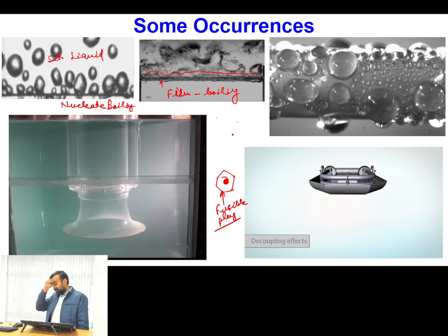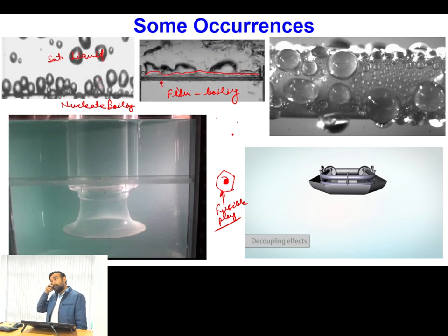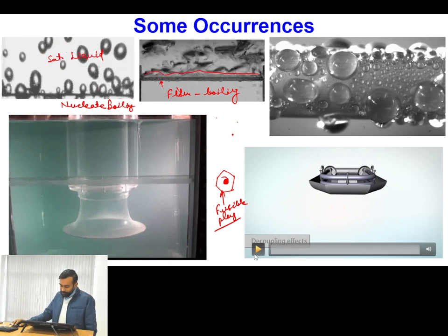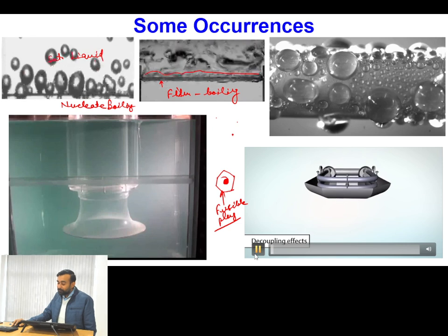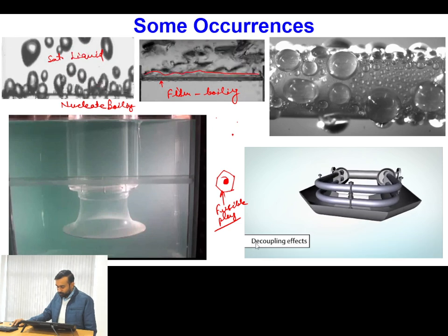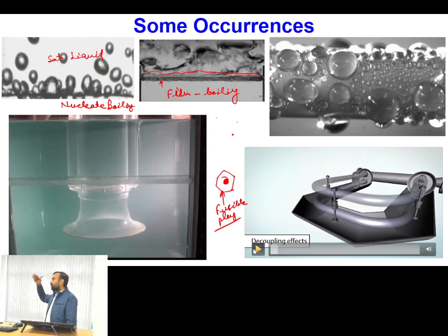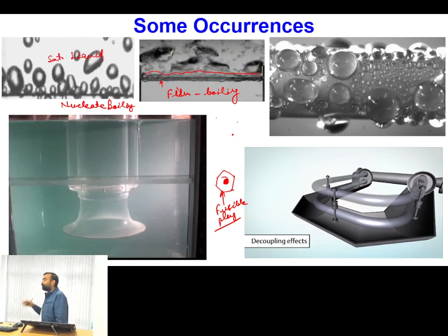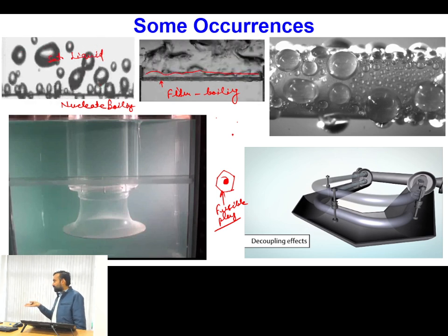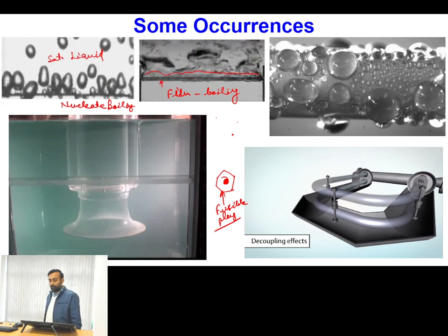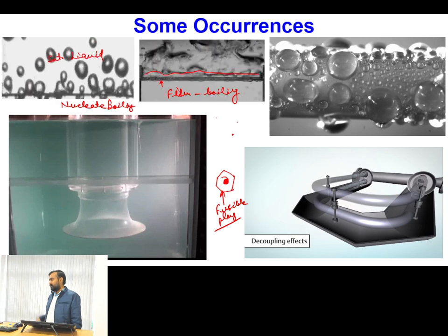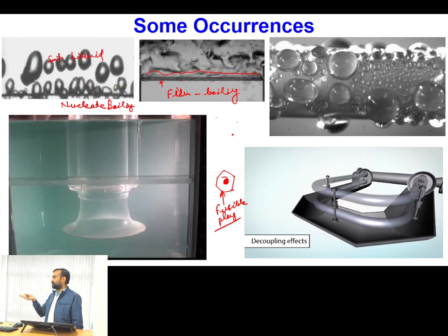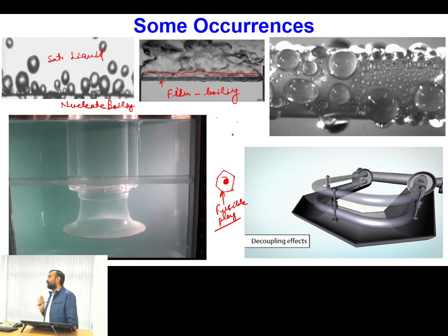So a Coriolis mass flow meter is a device which works on the Coriolis principle. In this device, we have two tubes, and these two tubes oscillate, and their oscillation frequency depends upon the mass flow rate of the medium which is flowing through these two tubes. So if the mass flow rate is high, their oscillating frequency will be high. If the mass flow rate is low, their oscillation frequency will be low.